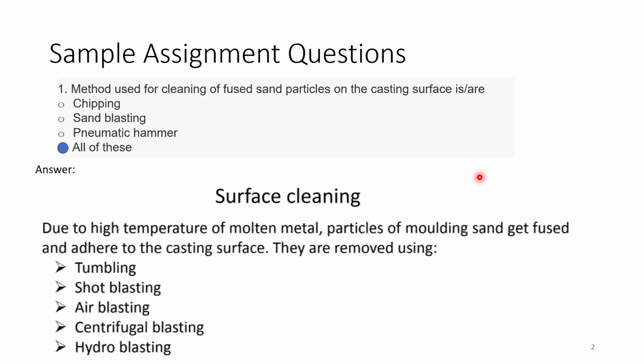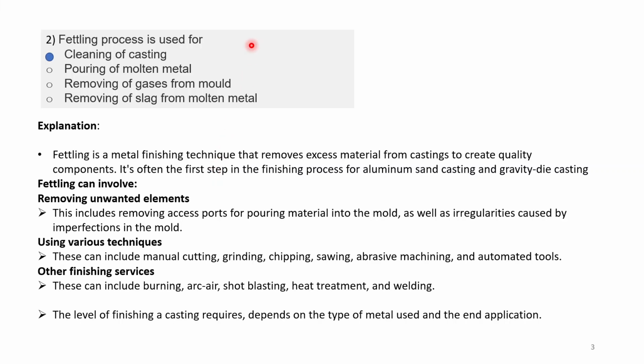After casting, you have obtained the casting, but it is still connected to the riser part and runner part, and there is also some fused sand on the surface. So for that you require cleaning of the casting. These are various processes. The next question was the fettling process. It is also used for cleaning of casting.